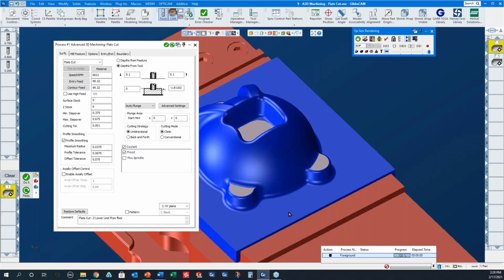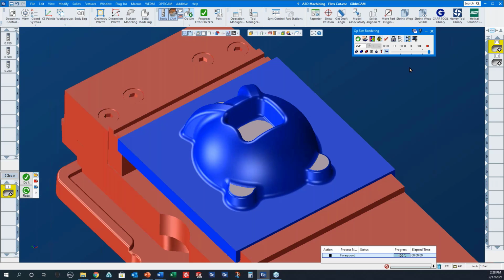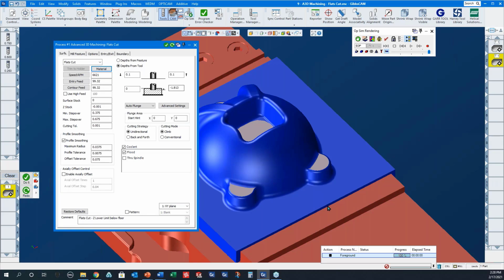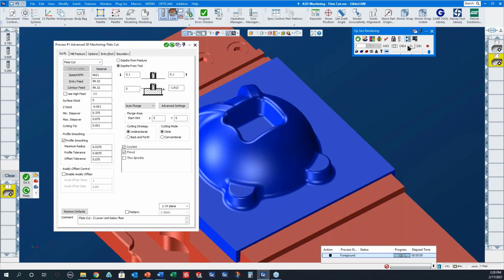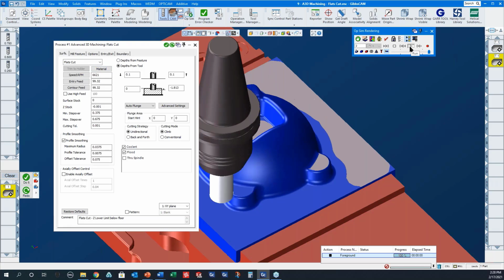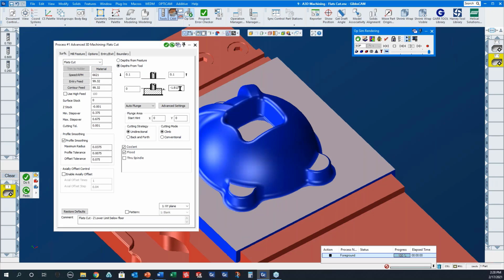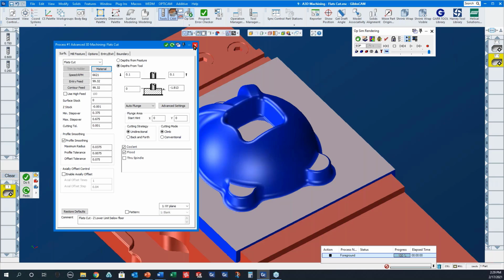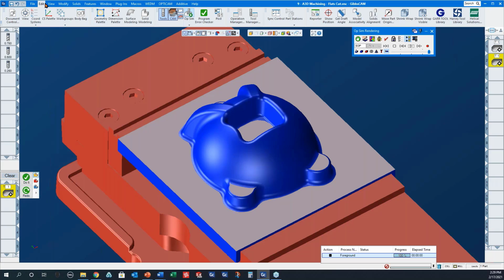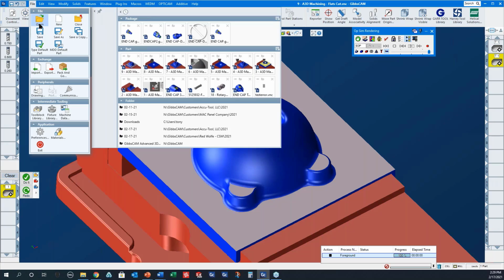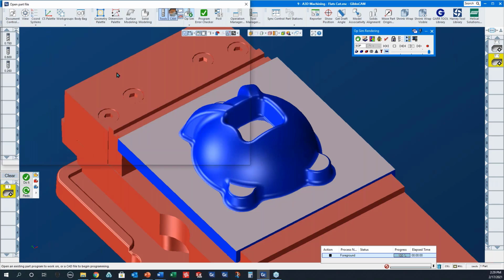But if you wanted to machine this surface as well, I just want to point out to you that you would need to set this Z value slightly below that surface. If we rewind and play this one, by setting that Z just 1,000 or so deeper, it actually cuts that flat as well. Flats cut's a really powerful tool.